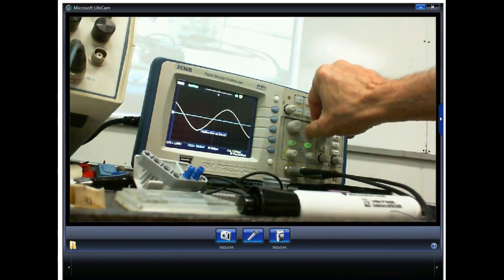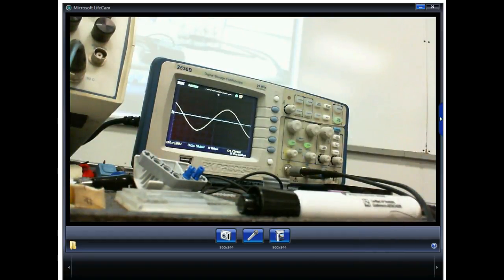Now we can't see it. Normally in AC, if the frequency is high enough, AC will couple through an open. So it's very seldom you actually see 0 on the oscilloscope when you're dealing with audio signals because it'll couple through opens, right? Now it's going to drop it down quite a bit. Okay, so what's next?